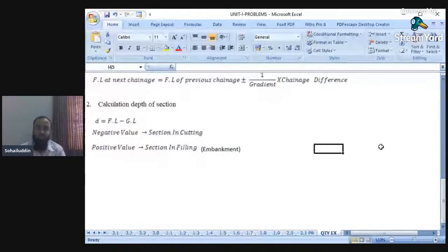But these 2 methods are most important: the mean area method and the mid-sectional area method. The depth method and area method are important, but the trapezoidal and prismatic methods are the fastest, and they are iterative or somewhat less precise methods, therefore these 2 are not used. The starting 2 methods are most important, and there is a compulsory question on them, the mean area method and the mid-sectional area method.